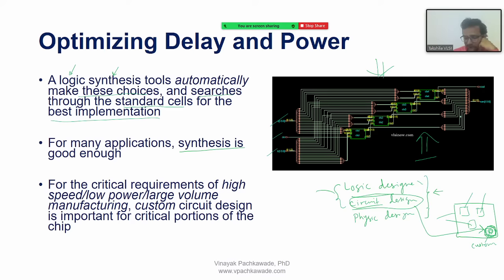For converting the behavioral code to the gate level netlist, from where do they get the technology library file? That is installed in their tool set, that is called as PDK, process design kits. So they use the tools in their set of tools. Their set of tools are different. Physical layout engineer set of tools are different. So in their set of tools, that library is already installed, that PDK is already installed, and from that they